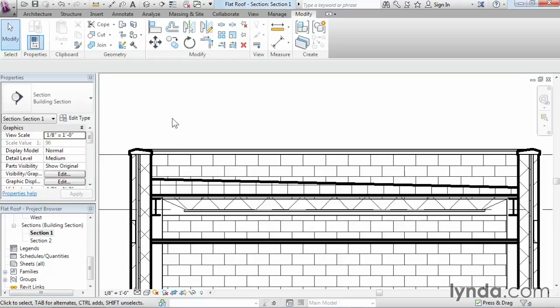You have to start with a completely flat roof. Then you have to use the shape editing tools to either add points or lines and manipulate where the heights of those points are. And then finally, you have to take your roof type structure and turn on the variable feature next to the rigid insulation component to get the taper to apply just to the rigid insulation.